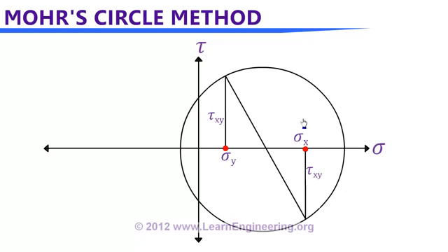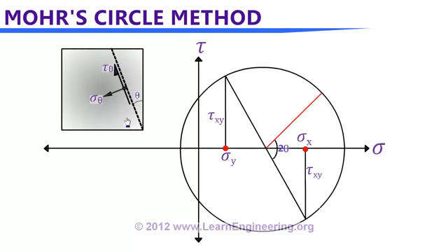And one thing to remember, the angle in Mohr circle is always doubled compared to the actual case. If this is your actual case where you have to find stress values at angle theta, then in Mohr circle analysis the angle will be doubled. It will be 2 theta. And the starting line of this angle should be the newly drawn diameter line.